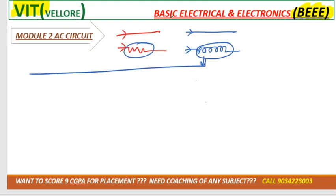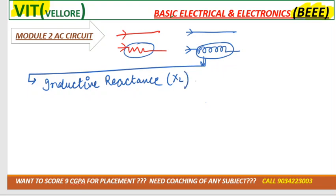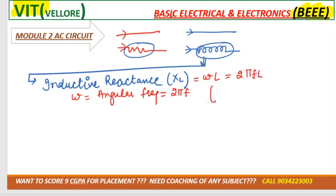So technically that resistance is known as inductive reactance. Inductive reactance is denoted by XL, right? And the XL formula is omega L. What is omega here? Omega is the angular frequency and its formula is, as you said, that is correct, 2 pi f. So XL is equal to how much? 2 pi f L.